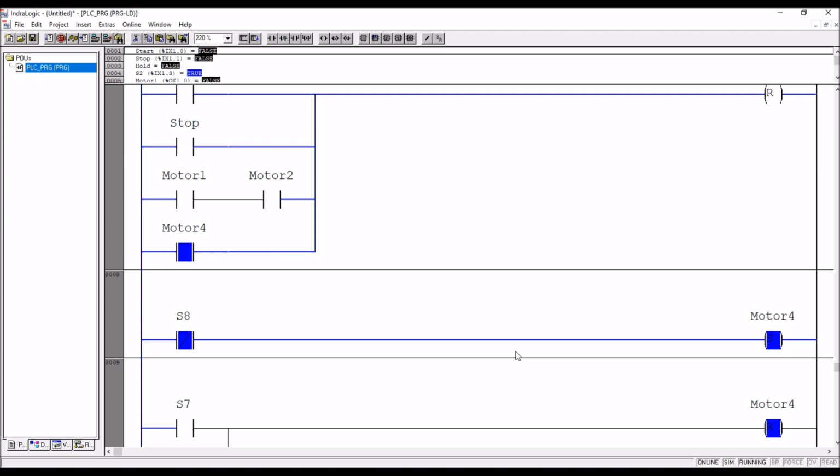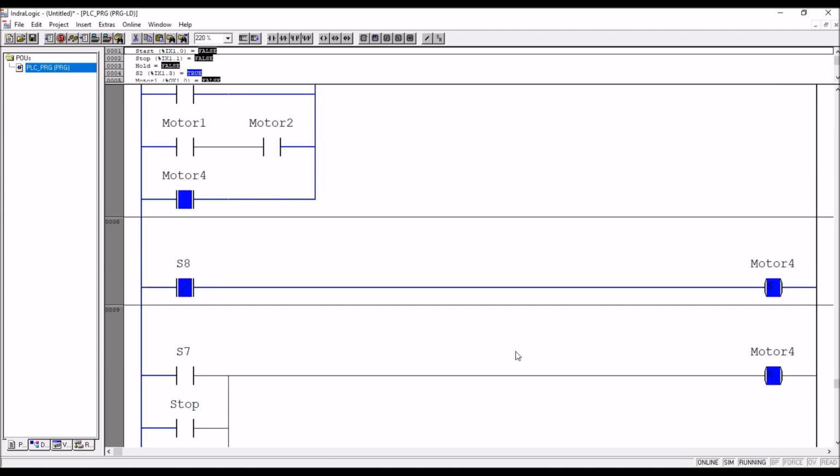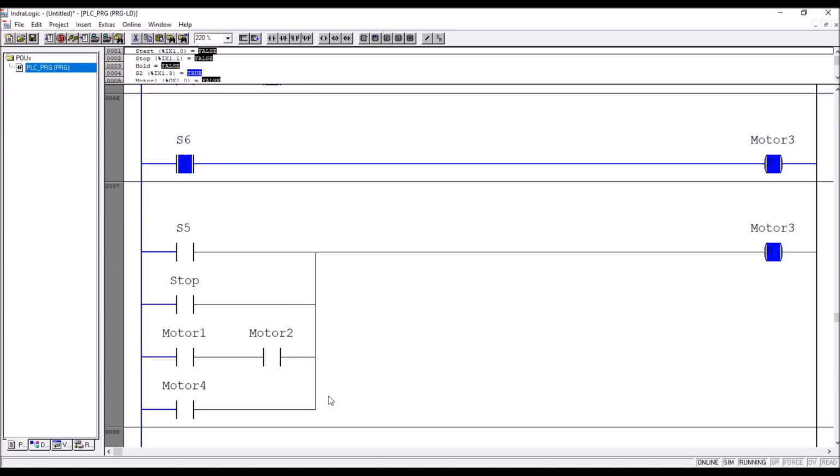We assume tank 3 also got filled. Say for example, first low level sensor is on, next high level sensor is on. Now only one tank needs to be filled, that is tank 3. Total load of pump 3 is 7 kilowatt, that is under the 10 kilowatt, so it is okay, it is getting filled.